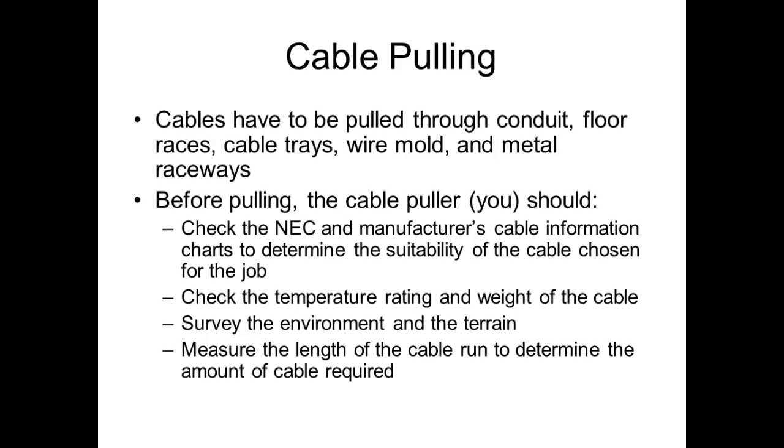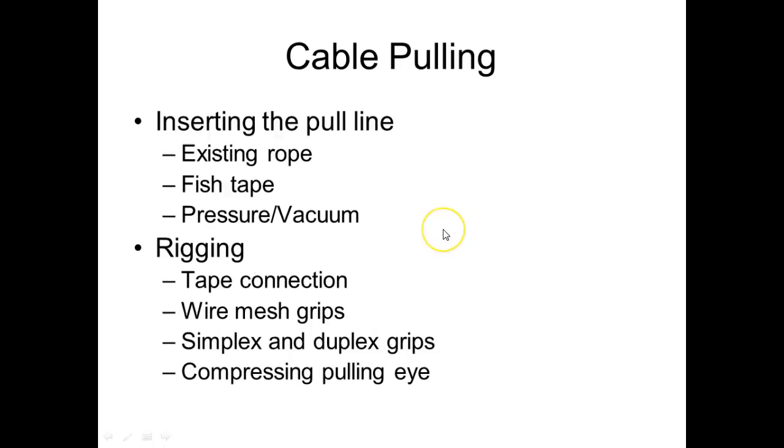Well, you couldn't pull this. If you can do it that way, what you can do, and we have people that do this, which is smart, is while you're putting your conduit together, put a pull string in there, and then that way you don't have to fish that fish tape through there. Because sometimes that fish tape isn't long enough, and sometimes it gets caught when you fish it through.